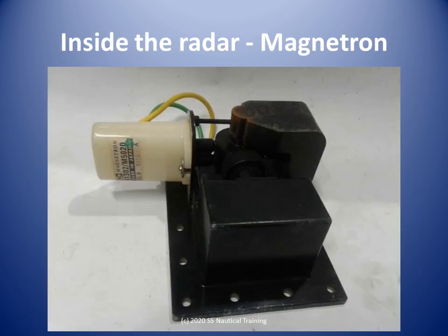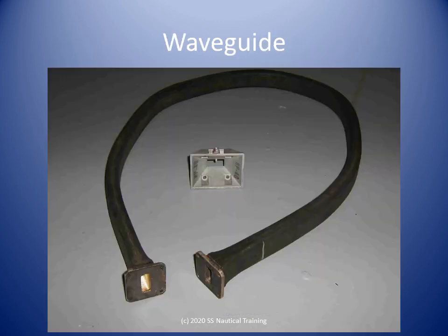The working process of radar starts with an oscillator known as the magnetron, which is a fixed frequency. The magnetron takes electrical inputs from a power source through a modulator and produces an output of electromagnetic energy known as pulse. These pulses are sent to the scanner or the antenna through a metallic tube known as waveguide. From the scanner, these pulses are sent out to the atmosphere.